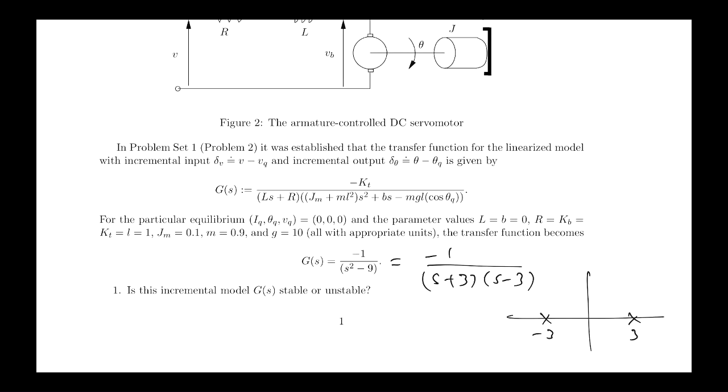And that's what we say is unstable. That should be consistent with your intuition that if I've got an inverted pendulum, if I tap it and don't do anything, it'll just fall down. So theta continues to grow as time advances, corresponding to the thing flicking around.